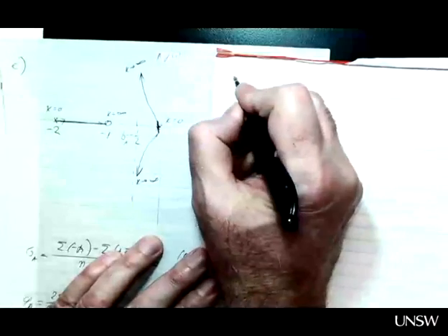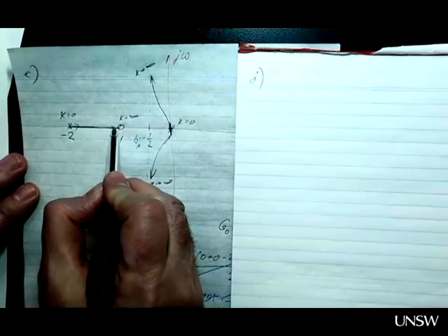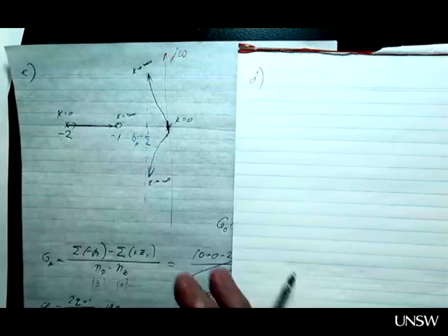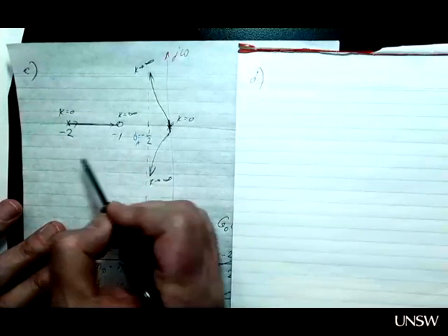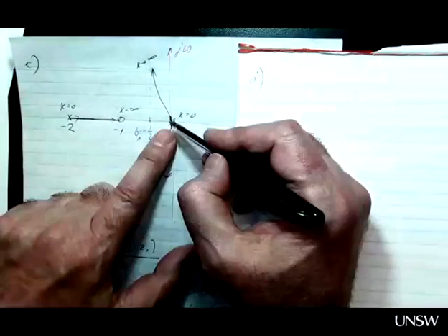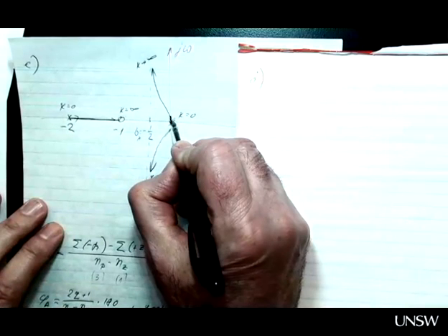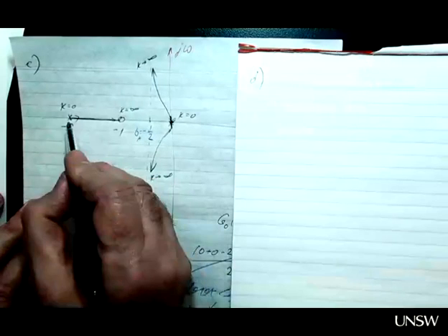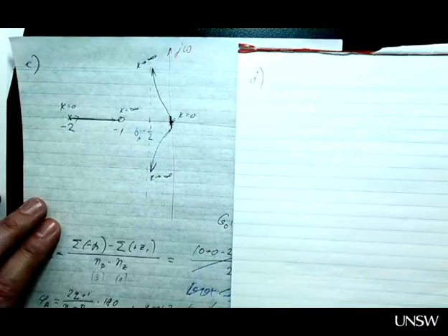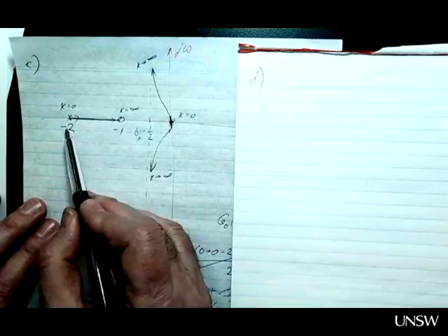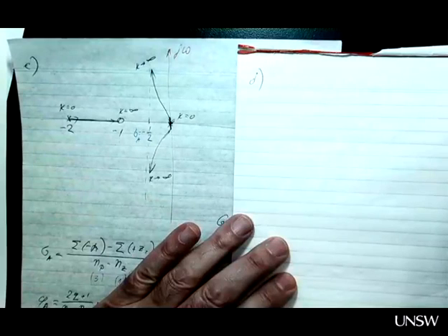Okay, so let's have a closer look at this root locus. This pole always stays on the real axis and always stays on the left-hand side of the real axis. So this pole is always stable. So this pole doesn't worry us very much. It's these 2 guys. Initially, when K equals 0, they are on the real axis, meaning non-oscillatory. Why do I say this pole doesn't bother us? First of all, it is always real. That means always exponential behavior, always non-oscillatory behavior. But second, because it is always on the left, it is also a stable pole. So the exponential is always like this, always decaying exponential, if you consider only this pole.